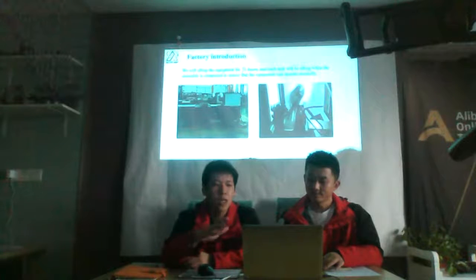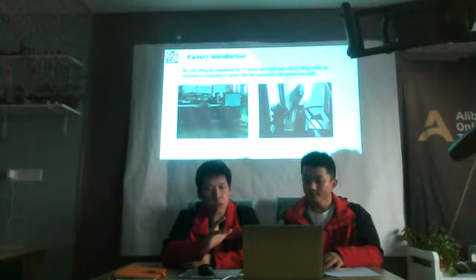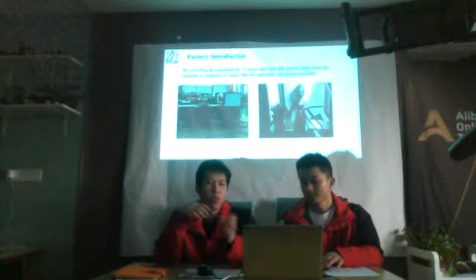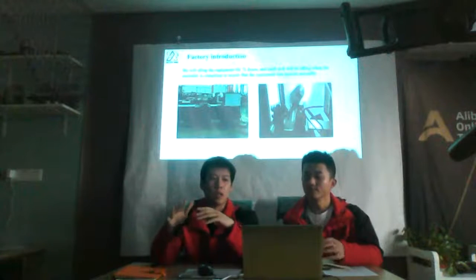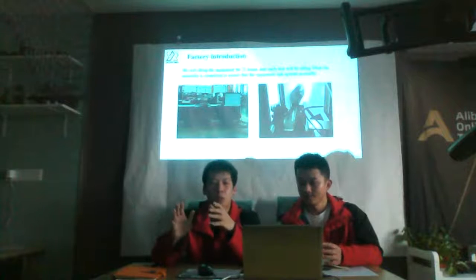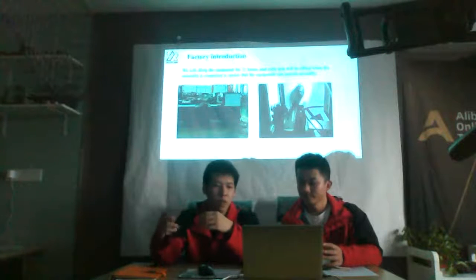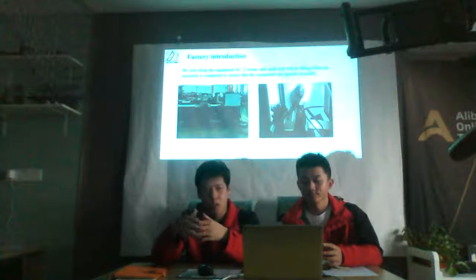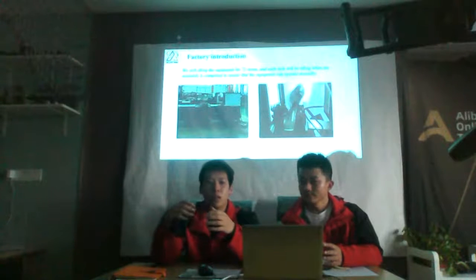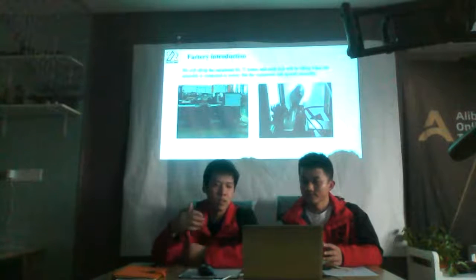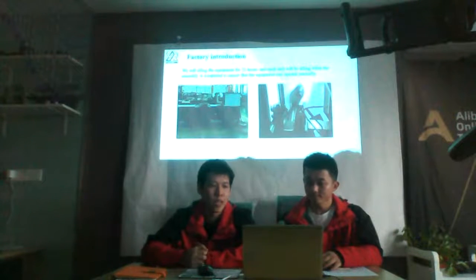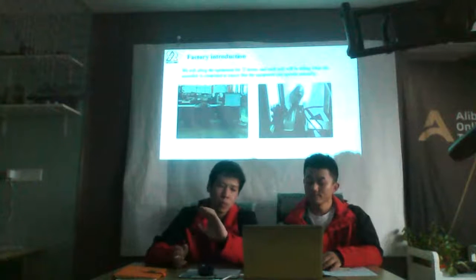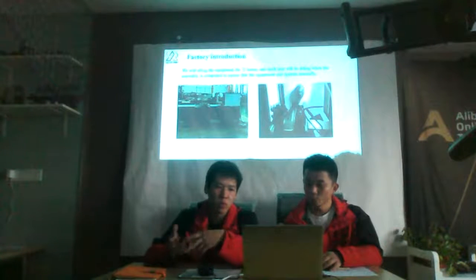And before the machine is delivered, we also do a 72-hour machine test run, which means the machine runs non-stop for 72 hours to test all the machine configuration, whether it can withstand this extreme condition, whether it can run for a very long time, and what will be broken, which proves it to you.